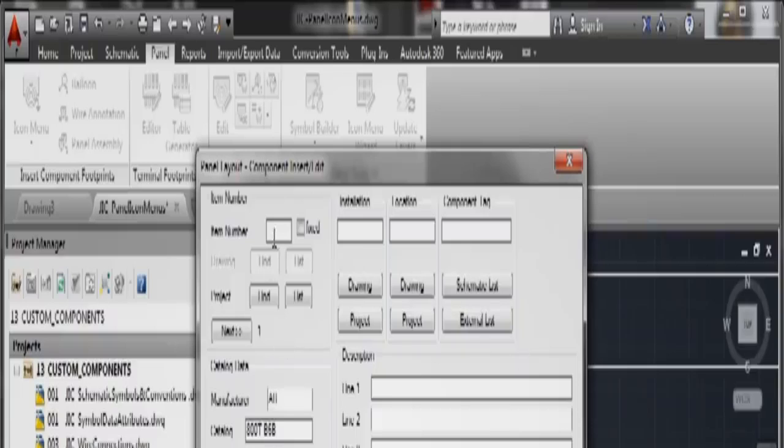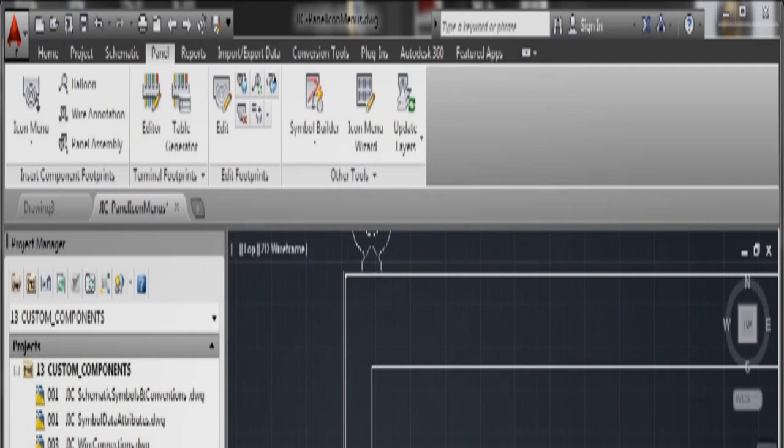There's the manufacturer. I might give it an item number. So this is a push button, so you might say it's PB001, for example. And you might give it a description, something like push button. Now we did cover this earlier, but what I want to do is just get across how important all of this information is, because it's showing all the ratings of that push button, the switch positions, drawing, project, group, everything's in there. So I click on OK, and it inserts that information like so.